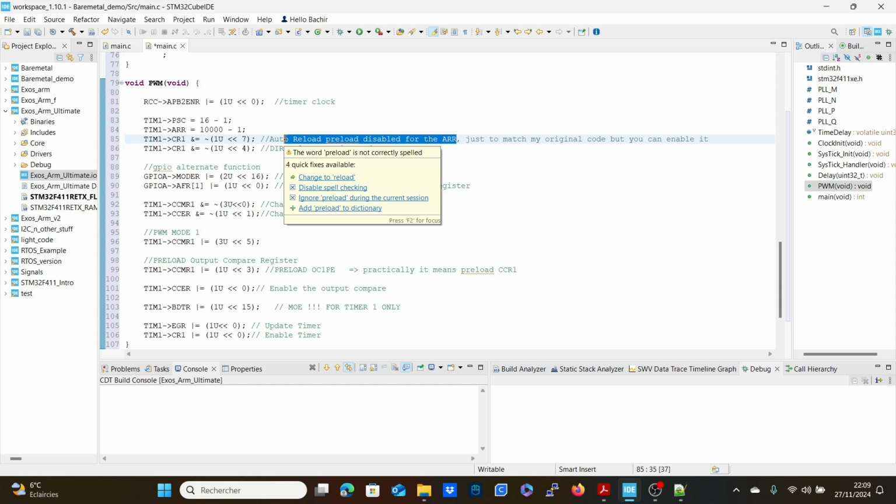What will happen is, if your counter is at 4,900 and something, and it will keep incrementing, even though you have changed the value to 10,000, it will overflow at the previous value, which was 5,000. And after that, when it starts counting again from 0, it will now overflow every time at 10,000 like you wanted when you changed the value.